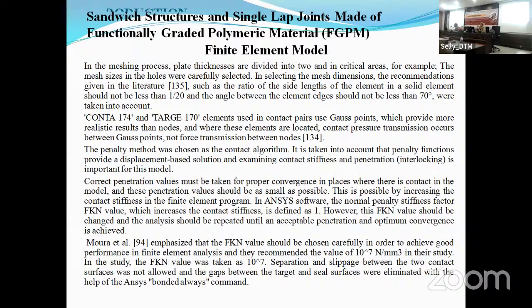In the contact pair, with the target element, the use of the Gauss points provides more realistic results than the nodes. This element is located between the layers, adhesive and adherent, and it carries the contact pressure.